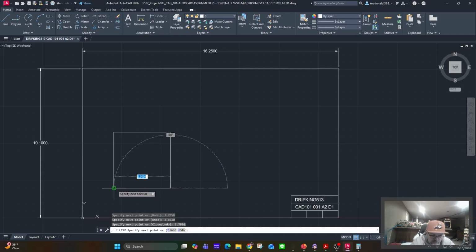And now we're just connecting the points. Should say 3.603 and 180 degrees. If it does, we can go ahead and hit enter. Or I'm sorry, should have clicked. So hovering over that bottom right corner, getting the green box, coming back over, we've got 3.603, 180, hitting left click. Now if I'm in manufacturing operations, I'm over at a mill. This is my material. This is my square that I'm going to start cutting away at.